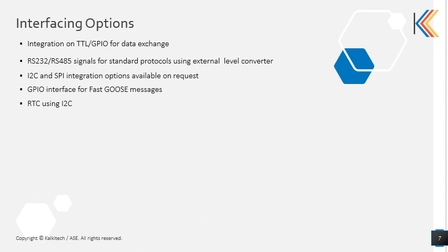Then this module has a Linux kernel, and it has its own time parameters kept inside. But if you want an RTC, which is especially needed when the device is booting up, that can be interfaced using an I2C interface, and we will readily provide the schematic to interface the RTC onto the device.